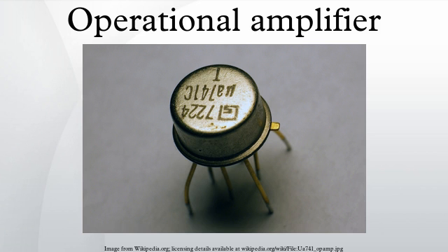A single-sided supply op-amp is one where the input and output voltages can be as low as the negative power supply voltage instead of needing to be at least 2 volts above it. The result is that it can operate in many applications with the negative supply pin on the op-amp being connected to the signal ground, thus eliminating the need for a separate negative power supply. The LM324 was one such op-amp that came in a quad package and became an industry standard.